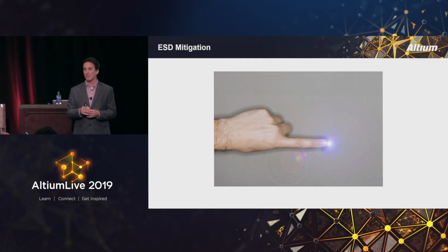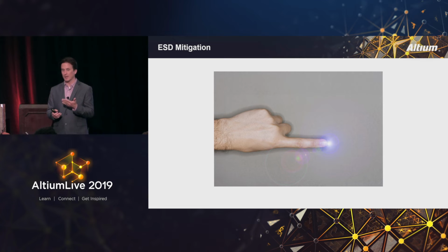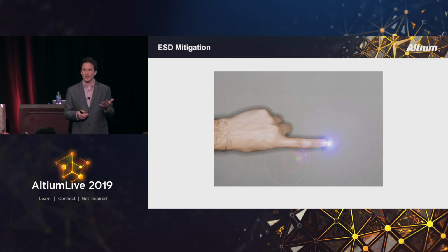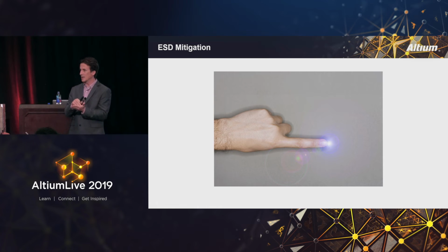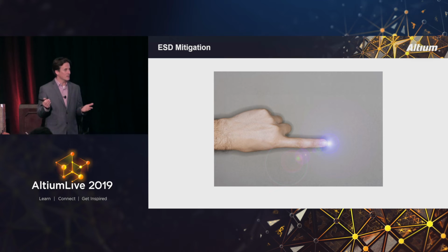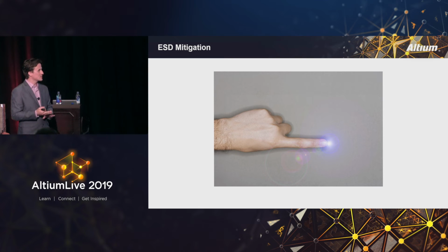Most likely what that means is there is some larger plate. In a lot of the TI calculators, they put in a plate, and the reason that plate is in there is to form a capacitive coupling with the ground. And that's where you dump your ESD. So you need to have a conversation about this.